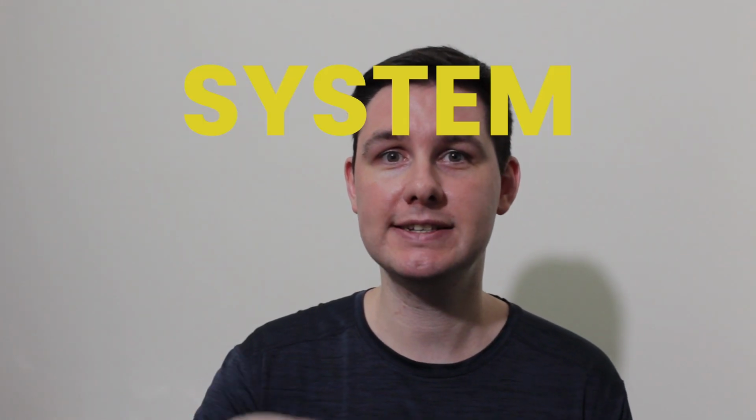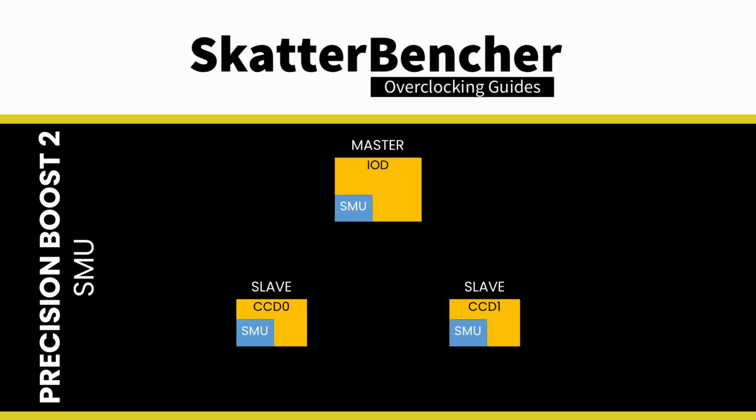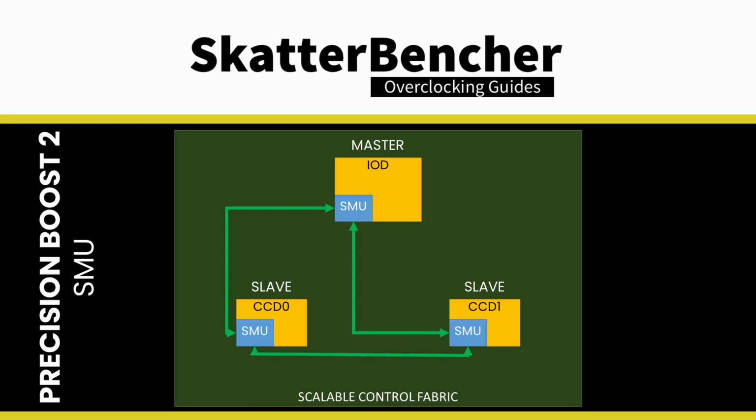SMU stands for System Management Unit, and every chip on your AMD Raphael CPU has an SMU on board. That means on Raphael CPUs with 2 CCDs and 1 IOD, you have a total of 3 SMUs. One of these SMUs will work as master SMU, while the others work as slave SMUs. Typically, the SMU in the IO die would be the master SMU. All SMUs are connected using a low bandwidth control bus called SCF, or Scalable Control Fabric.